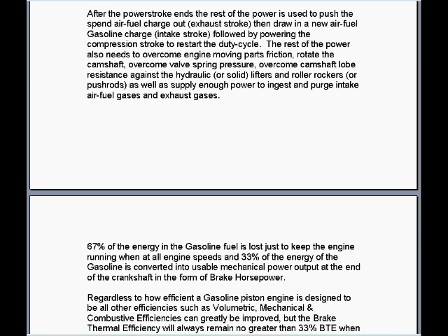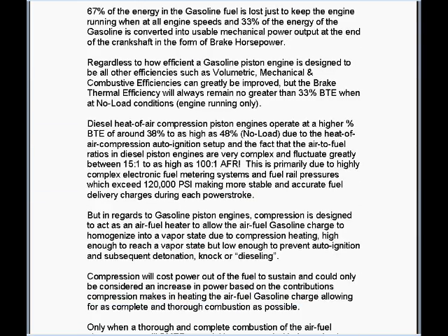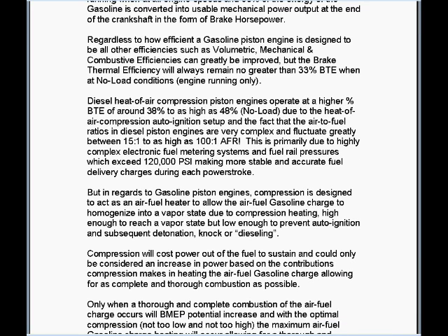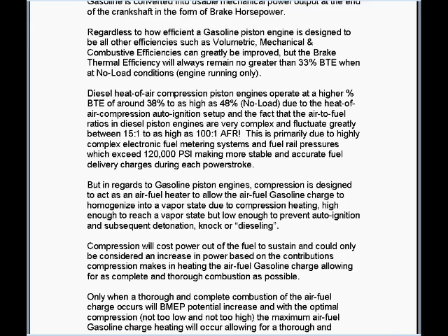The rest of the power also needs to overcome engine moving parts friction, rotate the camshaft, overcome valve spring pressure, overcome camshaft lobe resistance against the hydraulic or solid lifters and roller rockers or push rods, as well as supply enough power to ingest and purge intake air-fuel gases and exhaust gases. 67% of the energy in the gasoline fuel is lost just to keep the engine running at all engine speeds, and 33% of the energy of the gasoline is converted into usable mechanical power output at the end of the crankshaft in the form of brake horsepower.